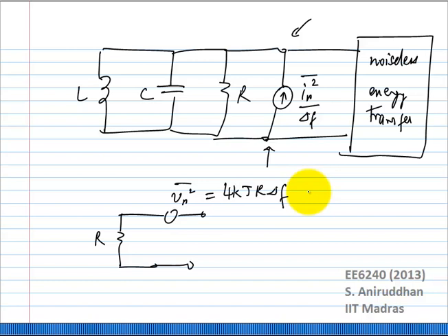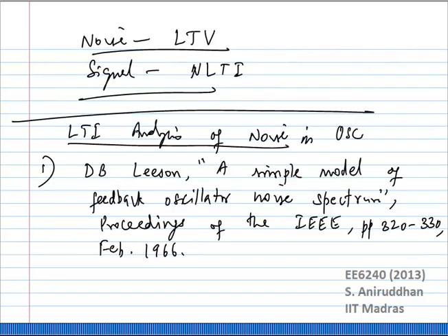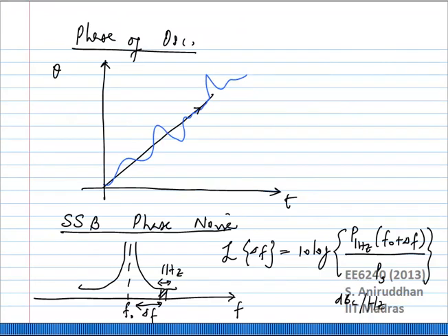Correct. The phase noise you can't talk about in terms of volts, because it's a variation. So it is something like radians. Sure, that's right. That's okay. So in fact, instead of voltage noise I can actually define phase noise even for a resistor in terms of this. Can I define this even at the output? I can't, because now I don't have a signal. But suppose I had a signal in series with this, I could actually define it in this manner, right?